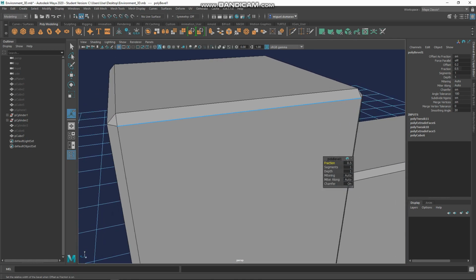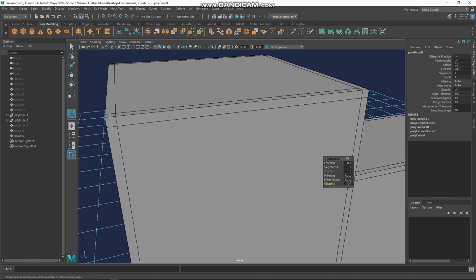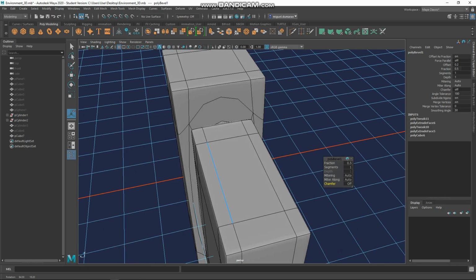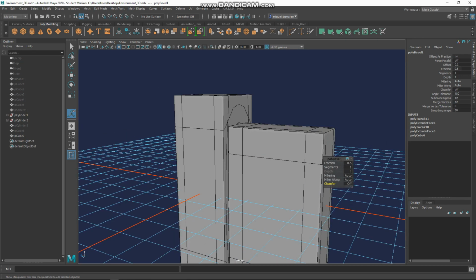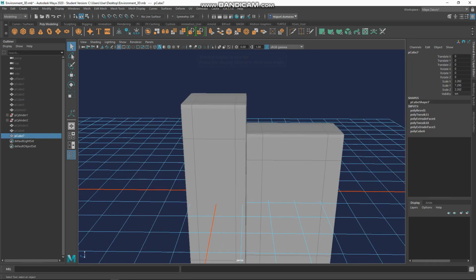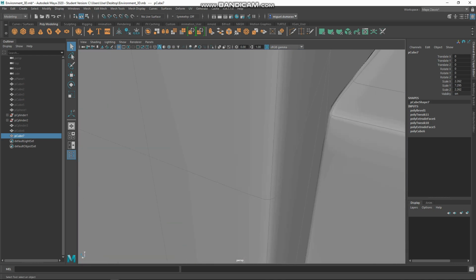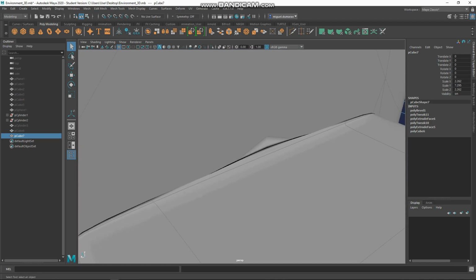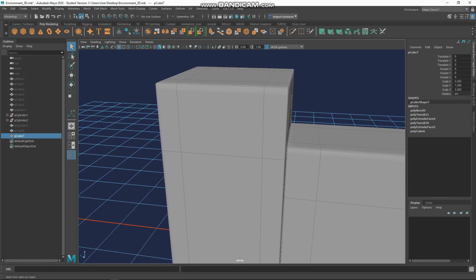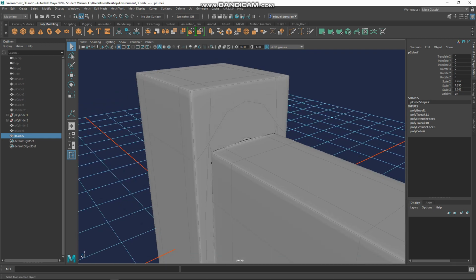Great. So I use chamfer off, and then I usually press 1 or 2, but I usually press 3 to instantly go to wireframe. You can see it's pretty smooth, and actually 5. So you can see it's pretty smooth now, but it has some weird artifacts on it. But you can clean that up later, I mean on Substance Painter when you do the baking. I can show you that, but just give me a moment, okay?